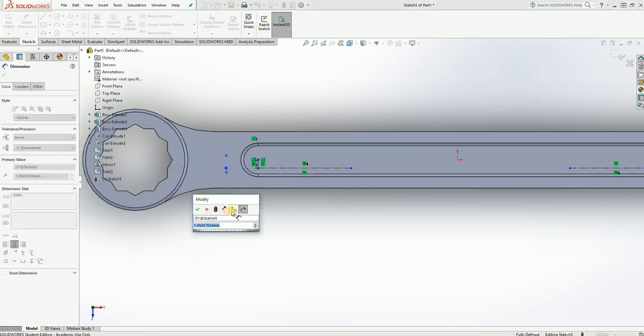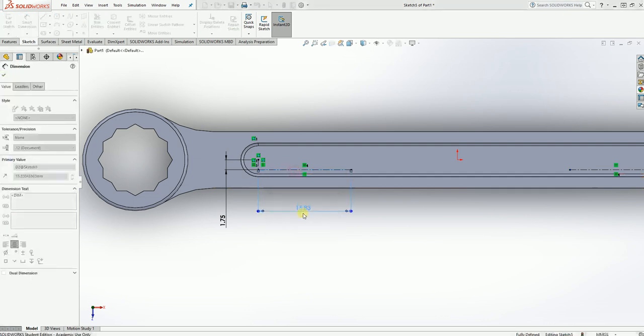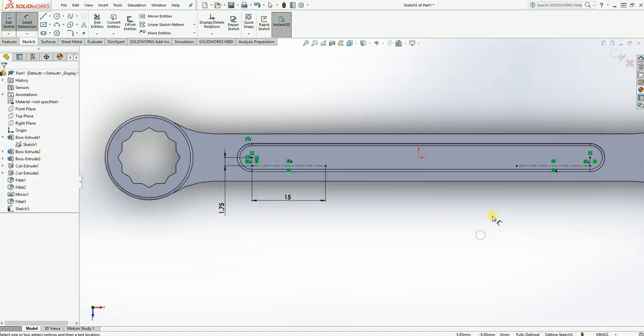Now I know my text is going to be 3.5mm tall, so therefore I want half of that for the bottom of the text, so let's do 3.5 divided by 2, and I'm going to want that to just come along 15mm just so it looks neat. Okay, so what I've basically done there is I've just created a line to write on, which is the best way to describe that really. So we've got text up here,